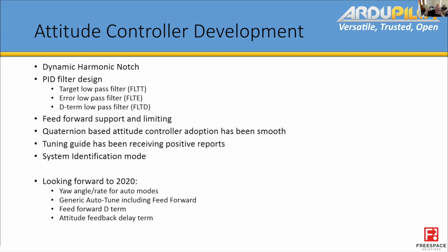But what we found is, as you make a really clean aircraft with very clean inputs coming from the IMU, we're able to filter out all the harmonics of the propeller. We then get down and start seeing things like the noise coming in through the EKF become really significant.